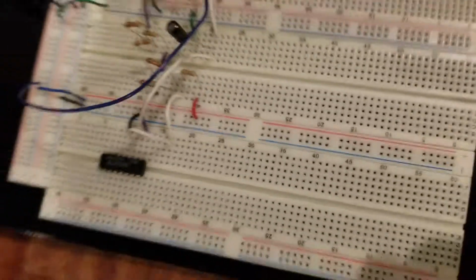So why it's useful is because it acts like a comparator in that it allows you to know whether you're at low or high voltages given these reference voltages that you designed for it. But since the Schmitt trigger also has hysteresis, unlike a comparator, it can deal with slowly rising and falling signals.